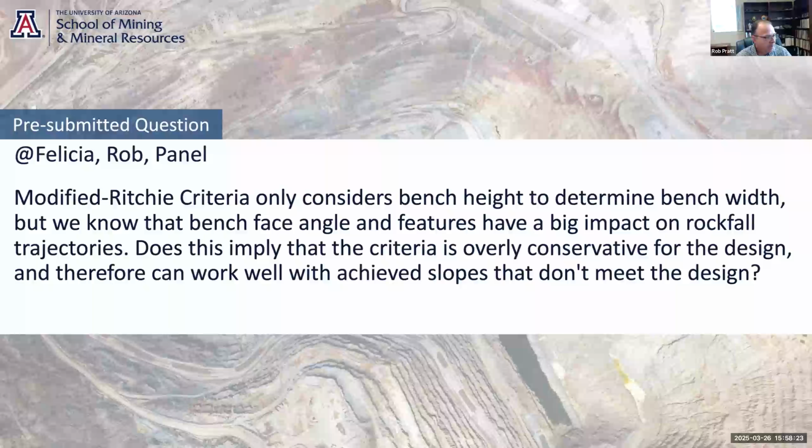And Carl spoke about the advent of technology for doing reconciliations and measuring the achieved configurations. It's nice to be able to measure what you actually mined and then compare that to this criteria to see, well, what does it mean to have a mine with a slope with your catch benches achieving this 80% of the time? What is the physical implication of that? What do the miners think of that slope, and how safe do the miners feel working below that slope?